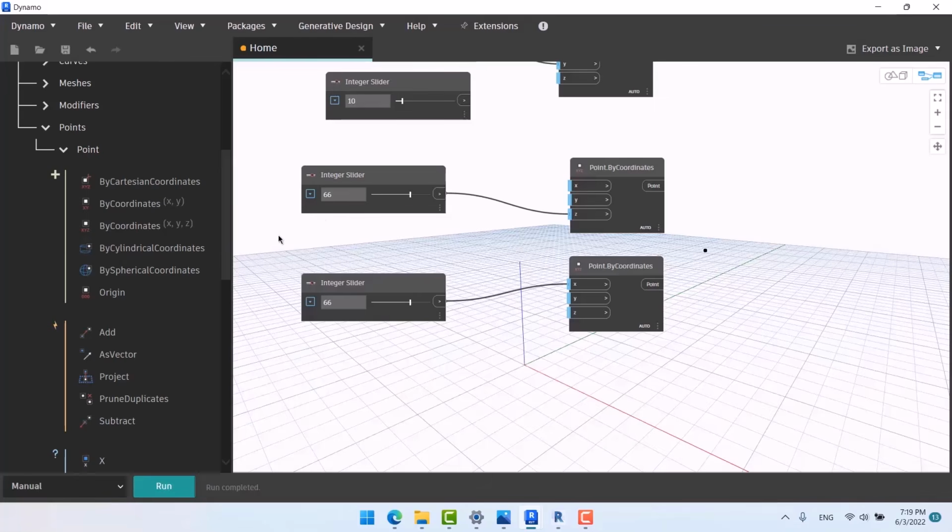Although this node and its number were not applied on the screen, Dynamo doesn't recognize their presence yet. Once you click on run once, it enters the circle of Dynamo nodes. From this time forward, it's gonna show the changes with orange color. So don't forget, if you add a node, you should click on run once, then from that moment on, it will show the changes.